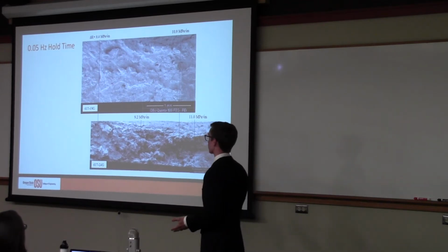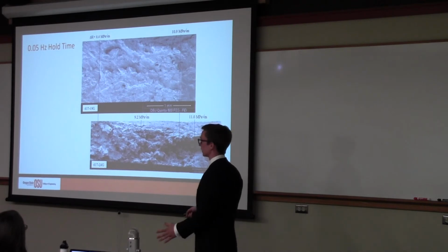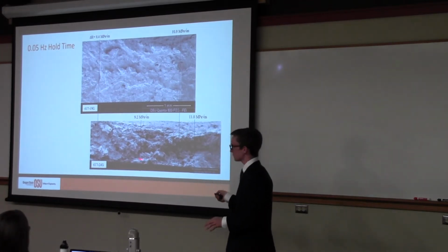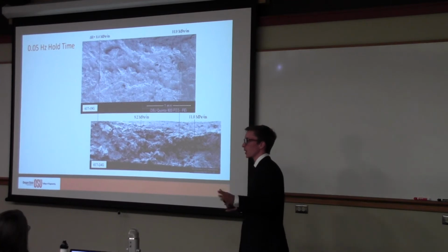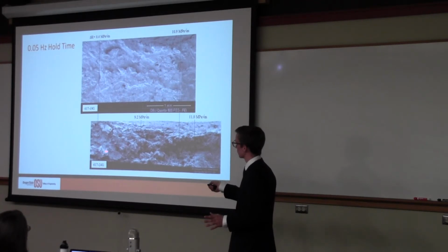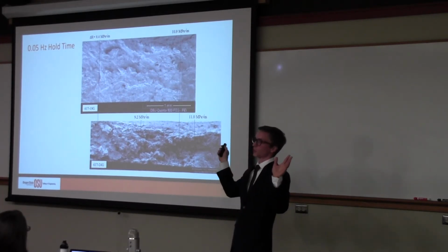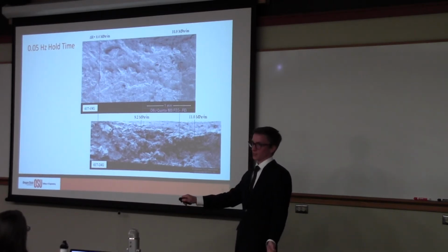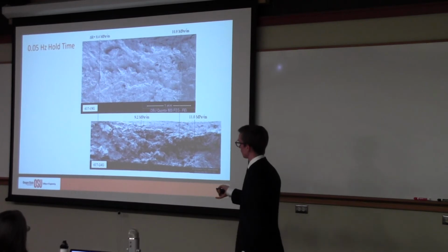But one thing, I'm going to gloss over this in the interest of time, I suppose. One thing about sample 61724 is that it was kind of shady experimental conditions. Okay, we had it at 800C. We had 2 millimeters of pretty rough crack growth, and then a limit tripped. It went down to 500 degrees Celsius. We held it there for 8 hours with no load because I wasn't here. I came in the morning and found it, and then heated it back up, turned it back on, and then all of a sudden it tripped to a much, look at this thing, voids and roughness.